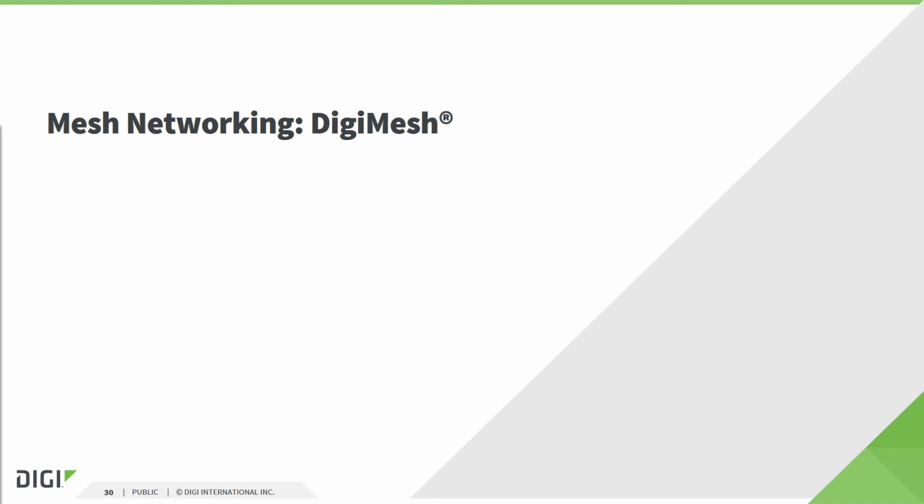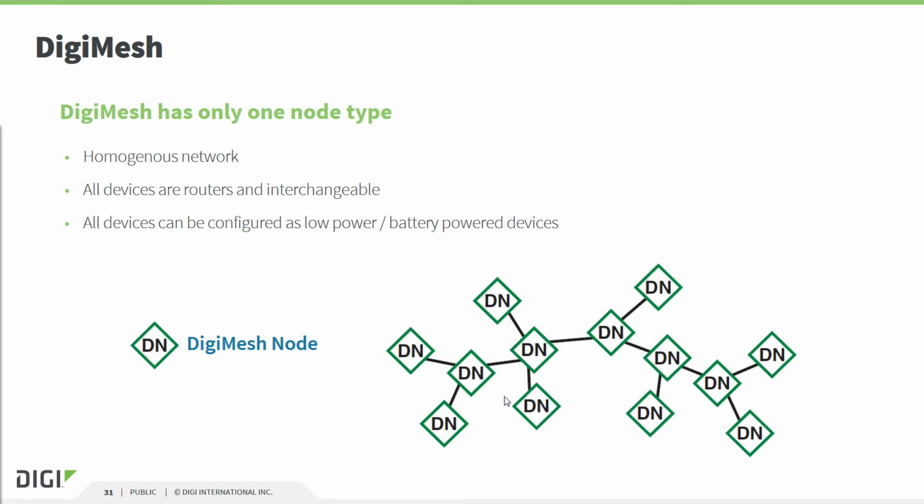Now let's have a look at DigiMesh. In this case, DigiMesh has only one type of node, so everybody is on the same level. All the devices are routers, and you can replace them wherever you want. The additional benefit with DigiMesh is all the devices can be battery powered, so everybody can go to sleep.